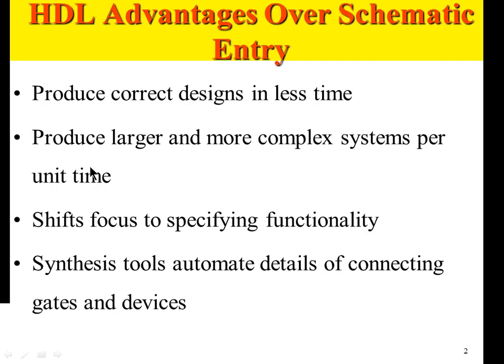So HDL, as we just described, stands for Hardware Description Language. It's a text-based method for describing hardware to a synthesis tool. So it's a language. You use an editor to write a design, and that Verilog file or that Verilog design is the input to the synthesis tool or the synthesis software, which will then convert that Verilog design to a gate level netlist. That's the first stage of hardware.